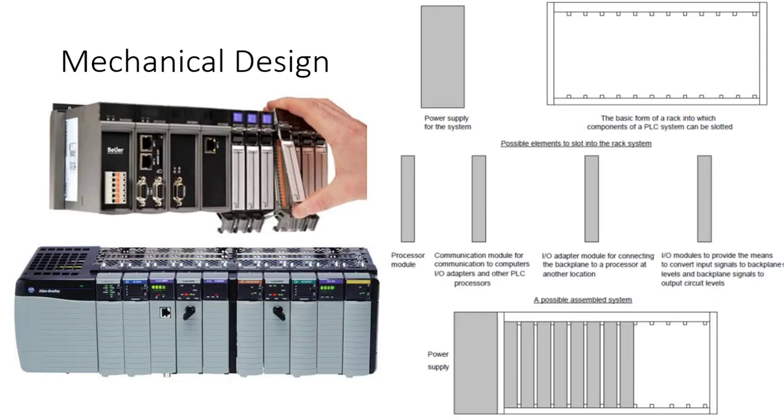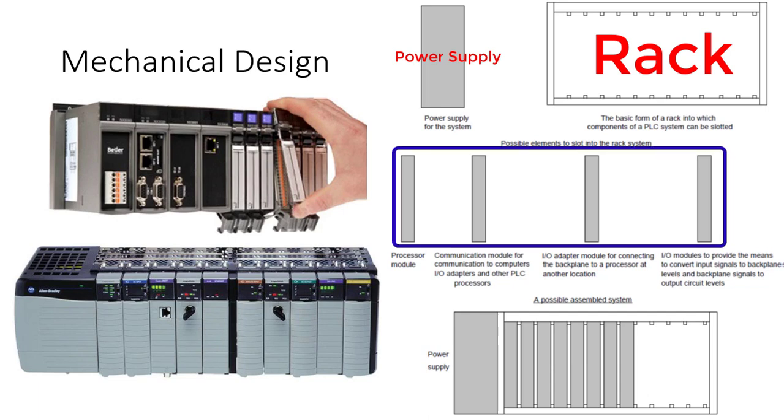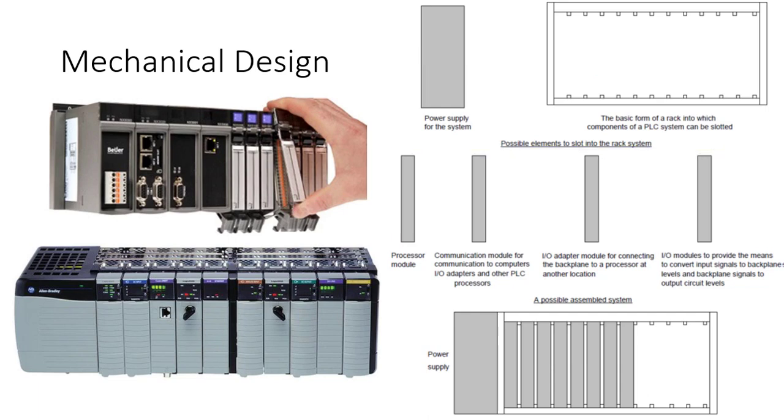This figure shows the typical construction of a modular PLC. The rack is powered by the power supply, and now you can attach the processor, communication module, and I/O modules. There are possibilities to expand the PLC beyond the given rack. However, it is normally not done because of the limitation of the processing power a certain processor has. However, sometimes an additional processor may be attached to expand the PLC beyond a single rack.